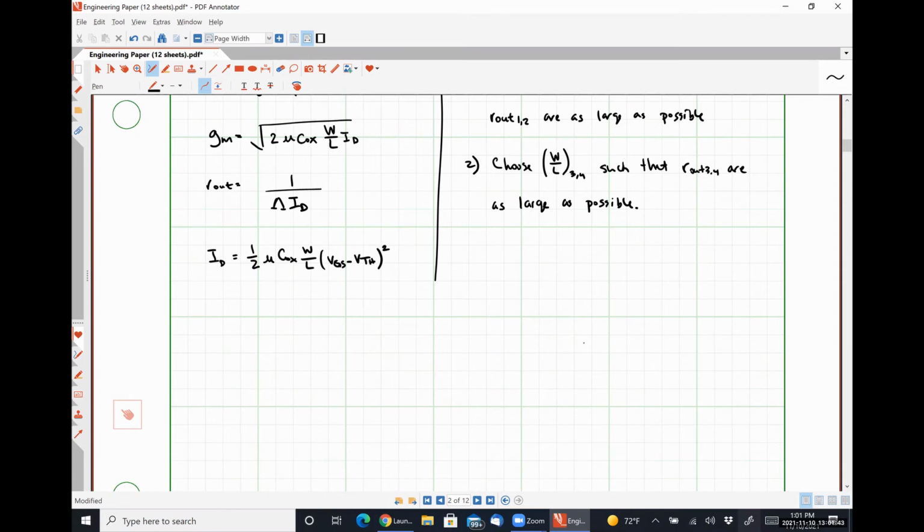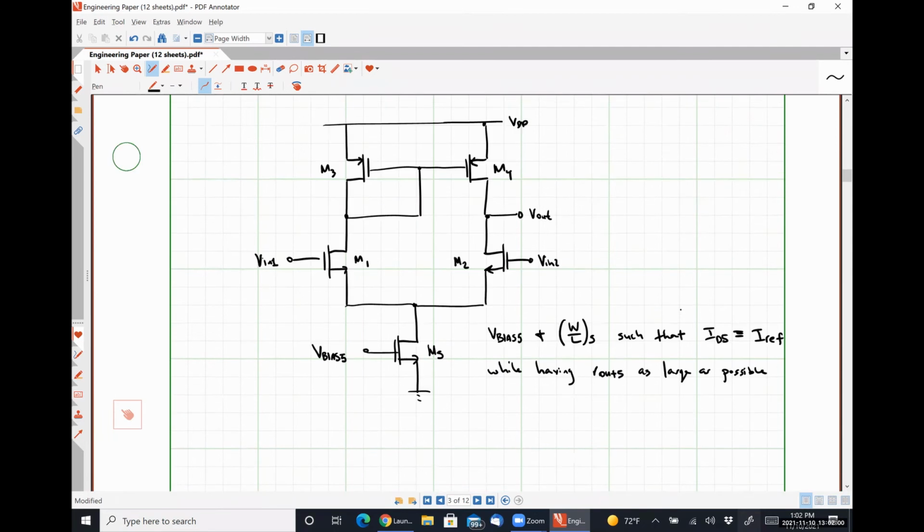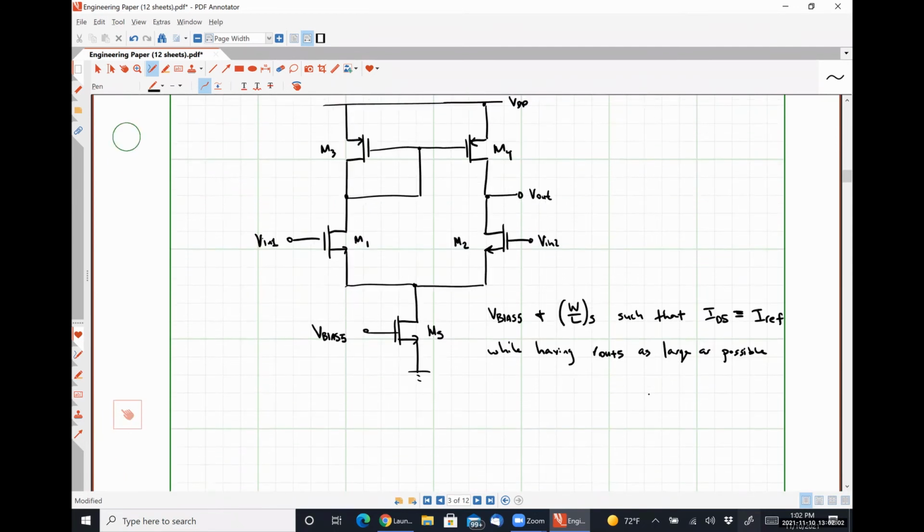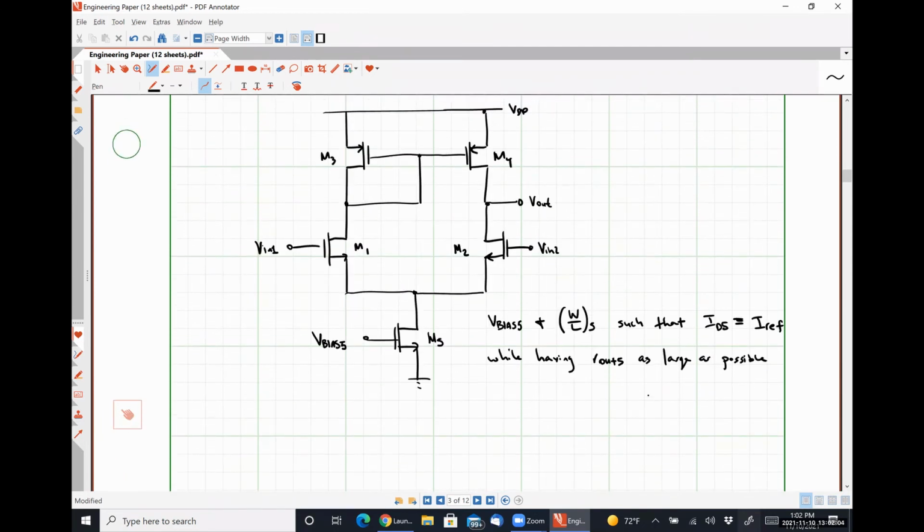So it is literally a fantastic move here that we have this dependency. It's easily solved. We just make the transistor have a very large channel. Or I think as we talked about it earlier, we could also cascode it and that would have a similar effect. All right, so these conditions are pretty easy to accomplish.